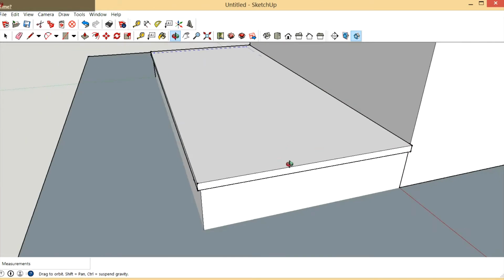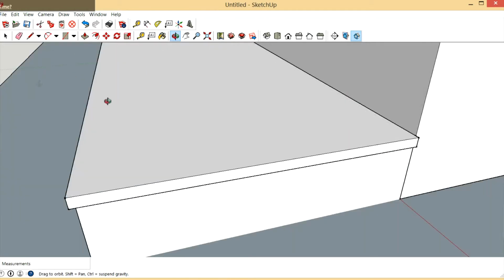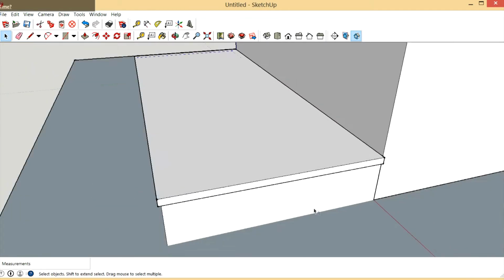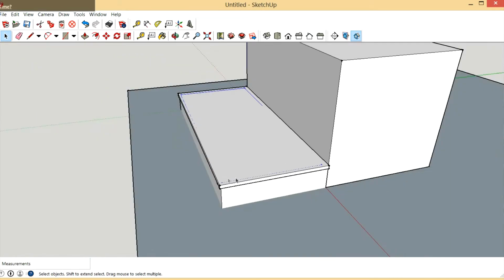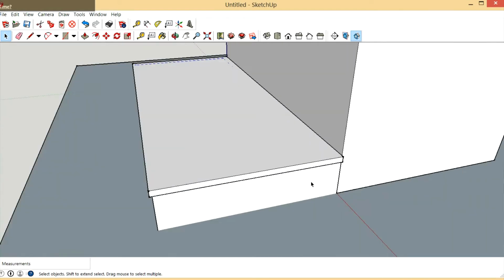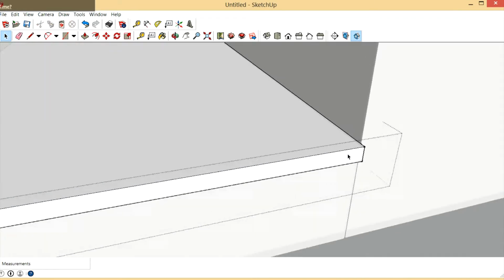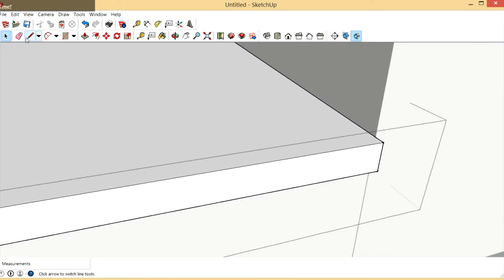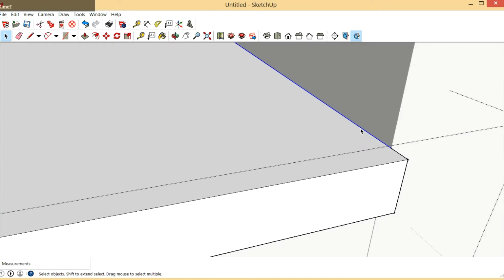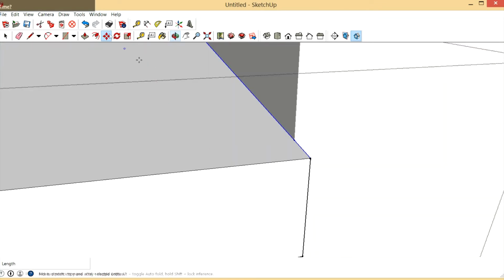The other thing I wanted to mention right quick too is that if you don't have anything to cover this slab, you don't want water running back to the house. So it wouldn't really hurt if you put about 3/4 of an inch of fall. So if we were just to grab this line and move it up, you just got to make sure you're grabbing the right stuff.